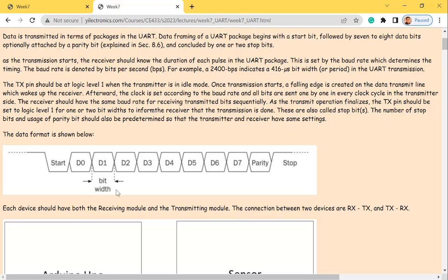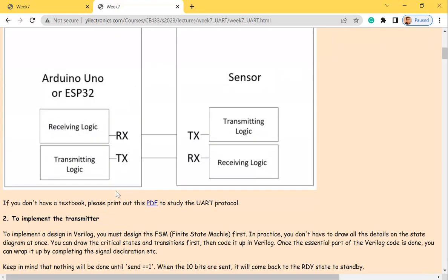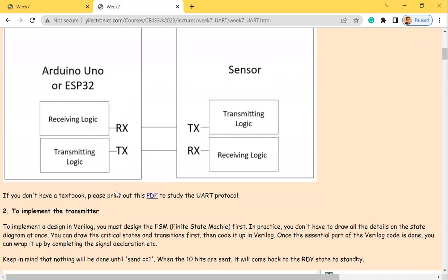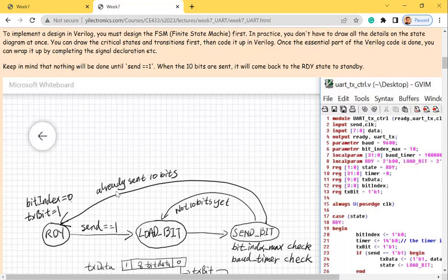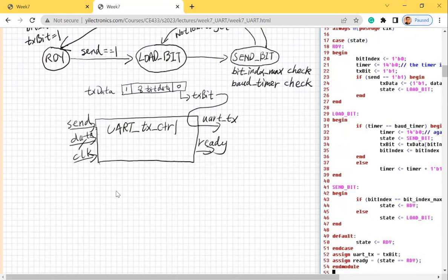Make sense? Why do we need 1 bit instead of 8 bits? 8 wires would take too many pins, right? It's super annoying. You don't have that many pins on the package of the chip. So it's serial communication, which means it's just one line. It's not parallel. And you need the clock to pump every single bit out each time. That's why we are doing this.